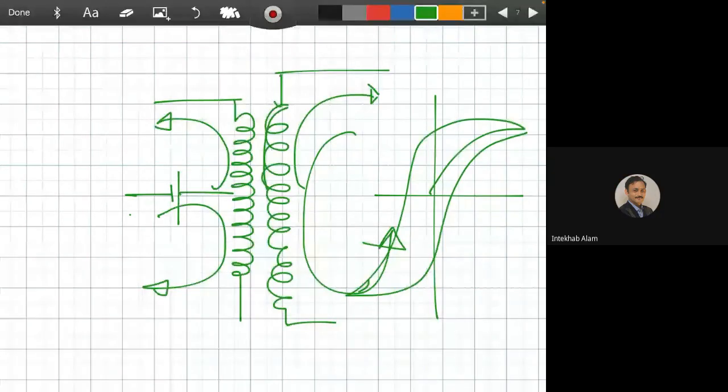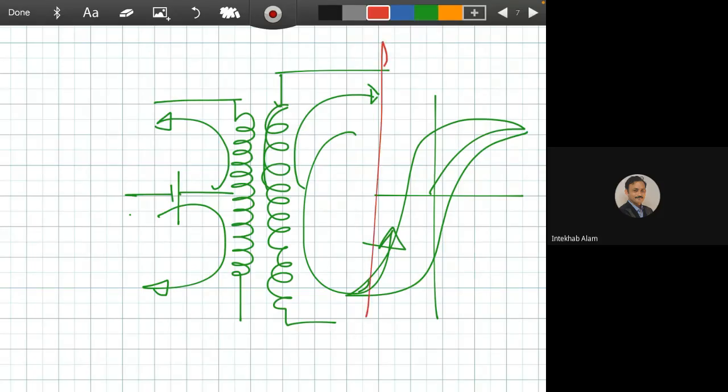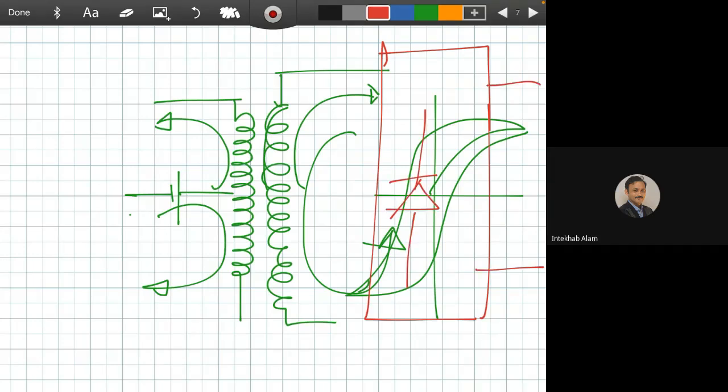No, it will not happen at the same time, because you are not switching on both switches at the same time. Once you are pushing, and after the completion of your pushing, you are then pulling. Sometimes you will find this as a push-pull converter also, because if you make a rectifier in the output terminal, this will be rectified. So there is a DC to DC conversion also, and you'll find it as a DC to DC push-pull converter.